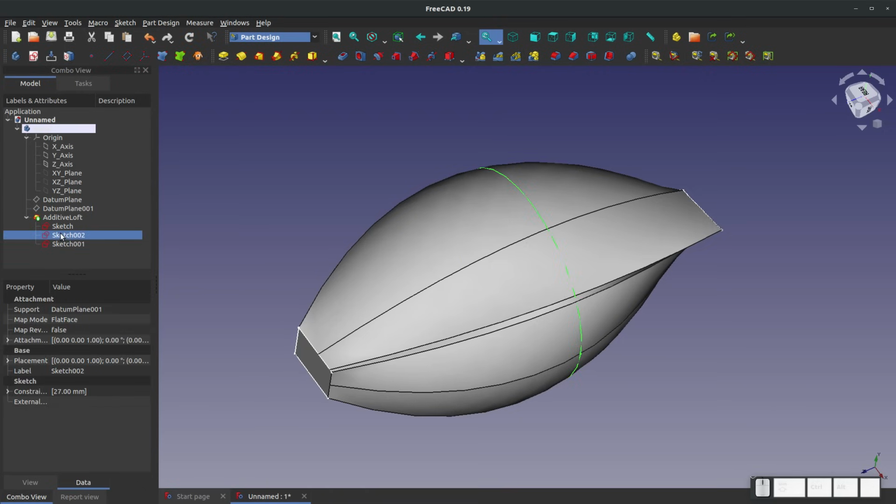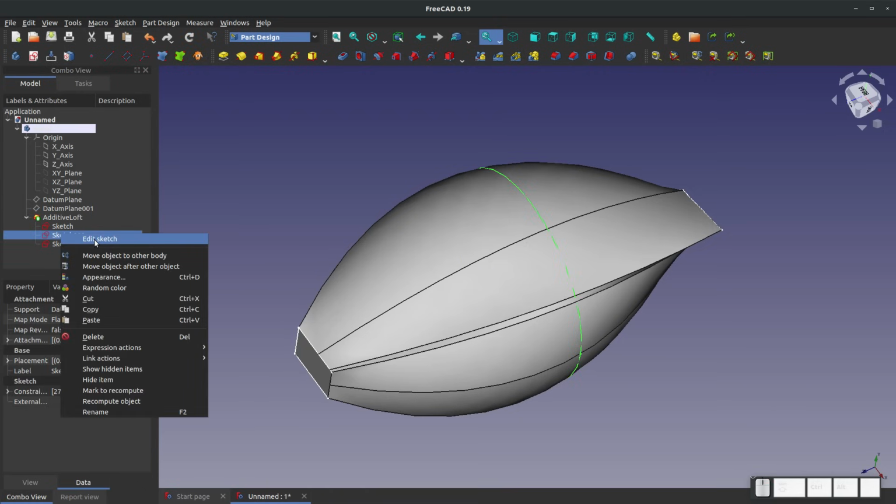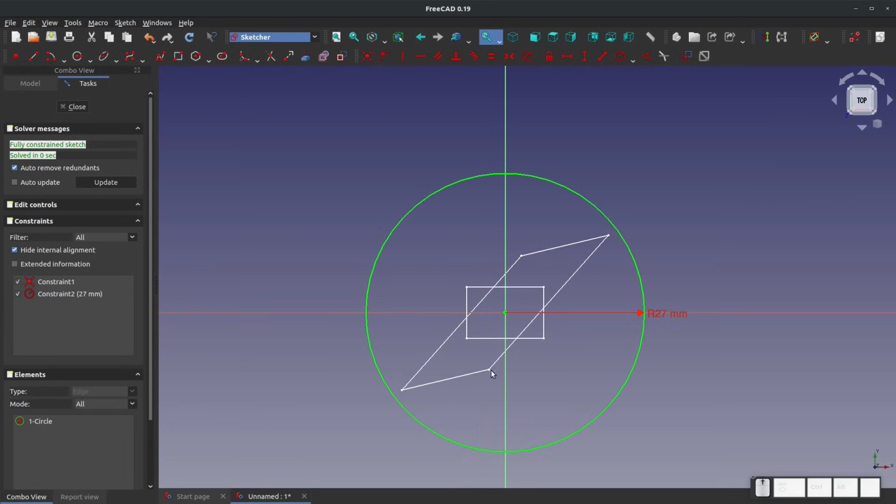Well, I can edit my sketch. I'm going to choose Edit Sketch, and I'm going to edit my circle sketch. And let's say that I want this circle for reference like we've talked about. So now this is blue. I changed it blue with this button. And we no longer have a circle that is driving. So instead of 4 lines to 1 circle to 4 lines, let's go 4 lines to 4 arcs to 4 lines. And that way we have the same number of sketch elements.